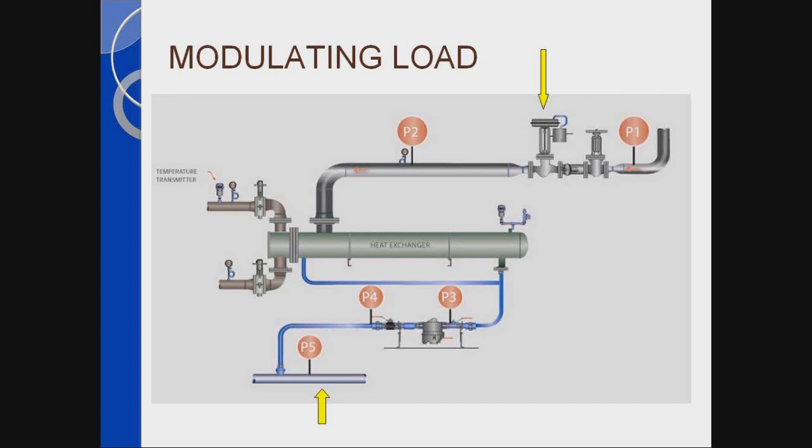The thing to remember is that coming out of the steam trap, or P4, going to the condensate header, which is P5, P5 must be 0 PSI. To make this process work, P5 has to be 0 PSI. One of the problems we find in process applications is pressure at P5, which puts pressure at P4, and we lose differential when the valve modulates down, which will back up condensate and cause water hammer. So remember, when you're putting a system in, P5 must equal 0 psi.